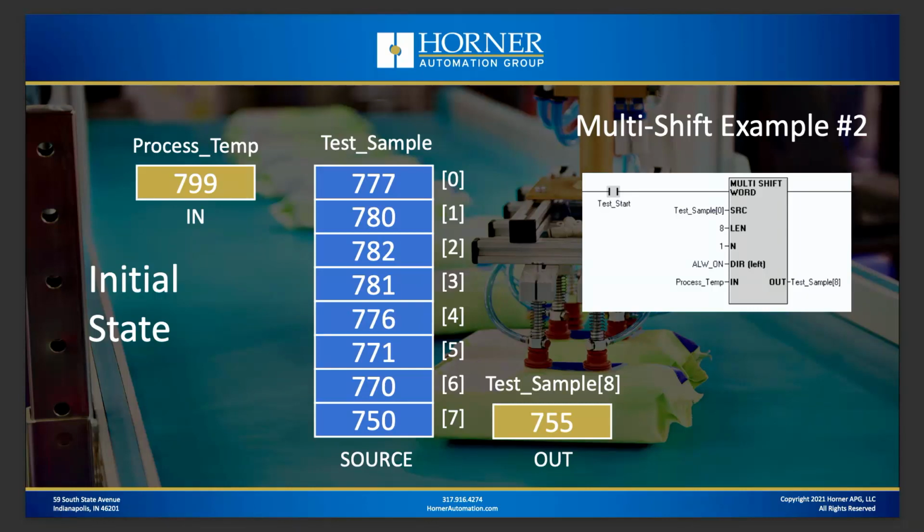Then we're going to start out by shifting to the left, which is the most common direction you would normally shift. The data we're shifting in is a variable called process temp. Our output that we're shifting out is just a variable called test sample. It's actually the same variable we're using to store all of our data. Instead of having a variable array of a total of 8 elements, I went ahead and tacked a 9th element on there, and I'm just using that 9th element for the output. Not something you have to do, but in some applications, the output of a shift register is very important.